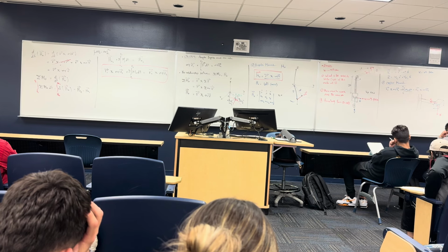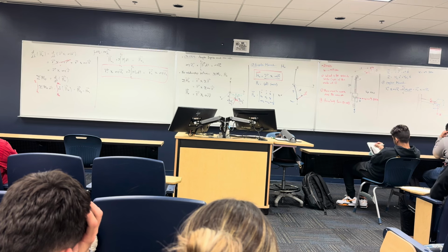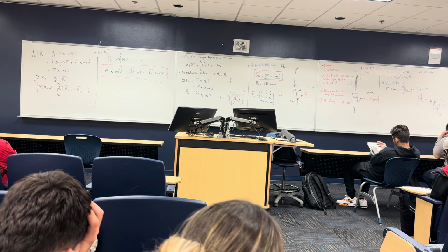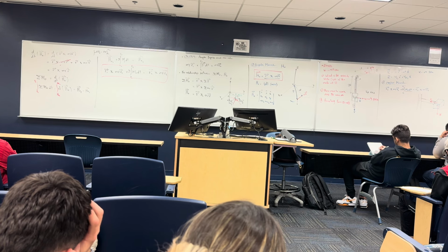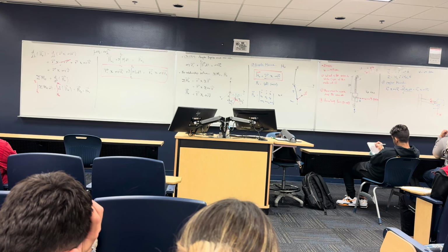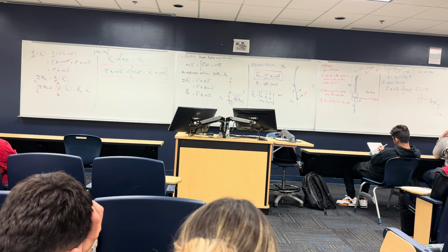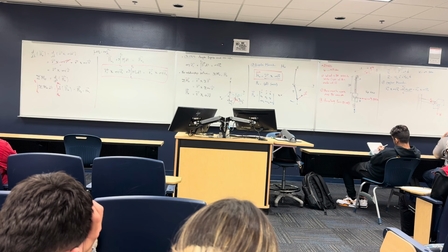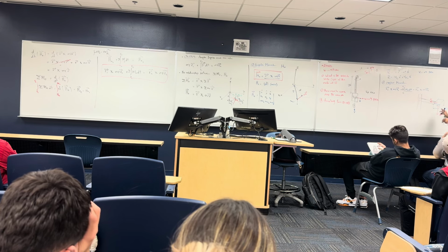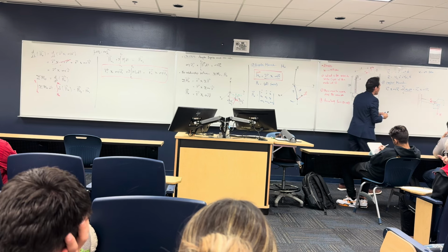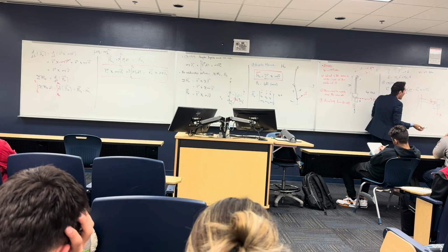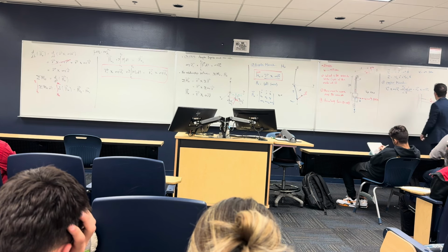If you have a force and you want to get the moment about a line parallel to the force, it's 0. Okay? But if it's this way, just be careful about the direction. Because as we said, the moment is the cross product of the r vector and the F vector. So here for F and the line that you get the moment about, the r goes in the same direction. Theta is 0. Okay, so the weight and the force don't make any moment, so the moment is equal to 0.